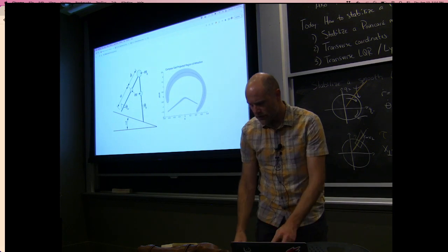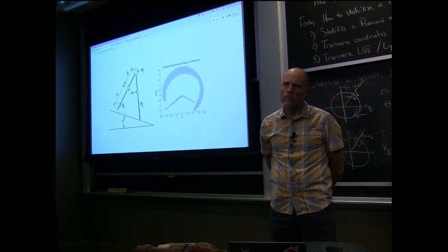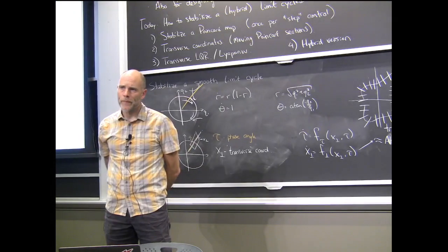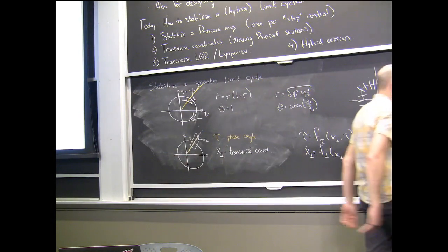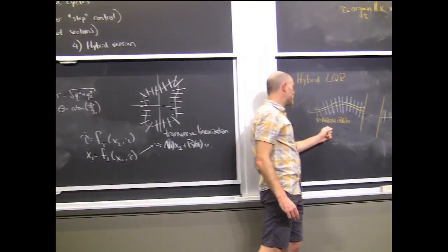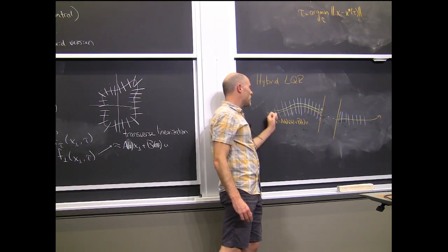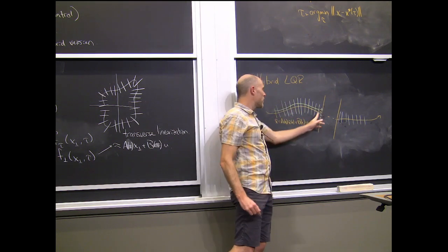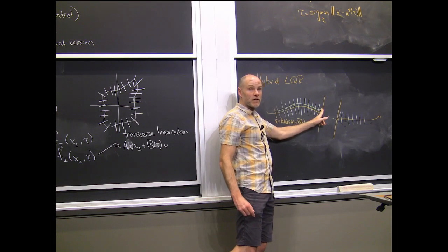Could you review again the complications that arise from parameterizing your LQR gains based off of state rather than time? So if it was a function of the full state, then you would have a time varying A and B matrix, yeah? And the problem is that at a certain time, the dynamics on your nominal trajectory could be very different than the dynamics on a perturbed trajectory.